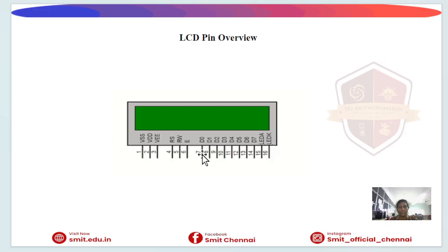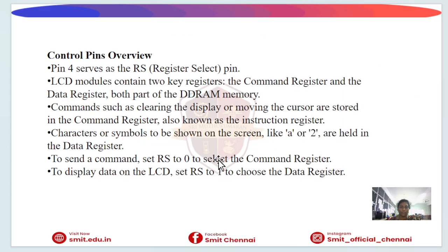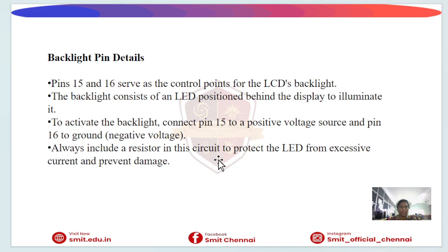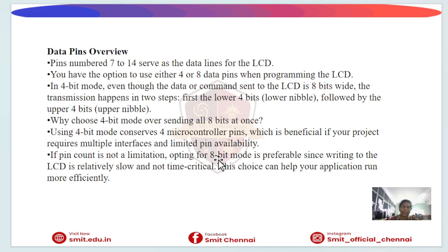Next one is the data pins, D0 to D7. These pins transfer the commands and character data. We have the pin description here. Two modes are available: the 8-bit mode and the 4-bit mode.